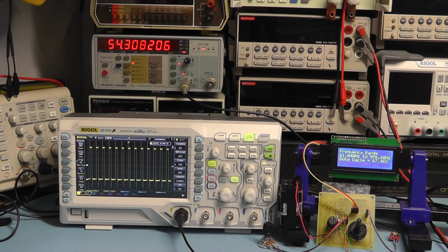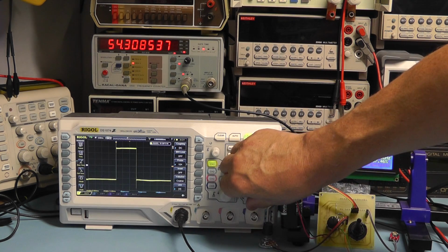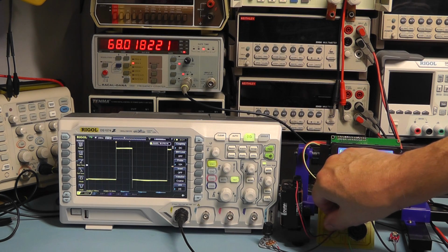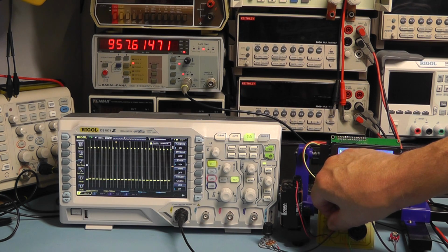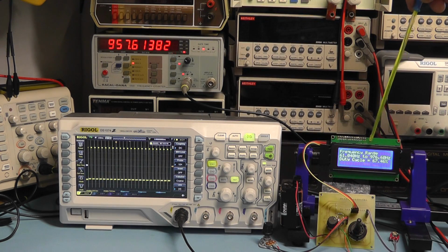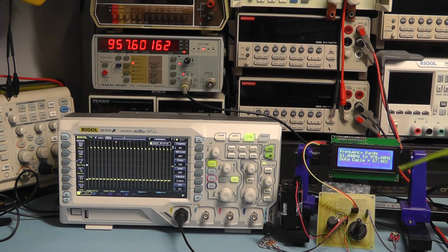So we're now at 61 Hertz to 976 Hertz. And there's the waveform again, and it's showing 54. Let me go to one end, the maximum end, and that says 957. According to the range, it should be 976. So our range is slightly out with respect to what we're seeing there on the frequency counter, but it's really just due to the resistor arrangements we have on the frequency control.